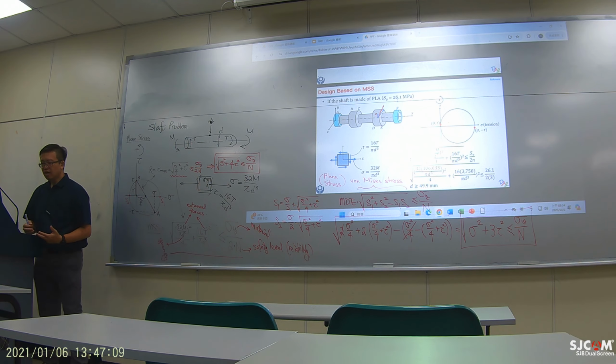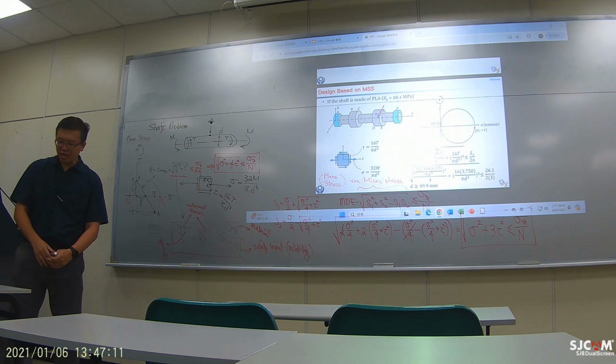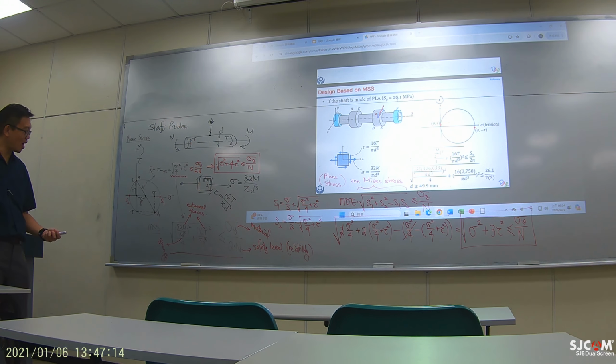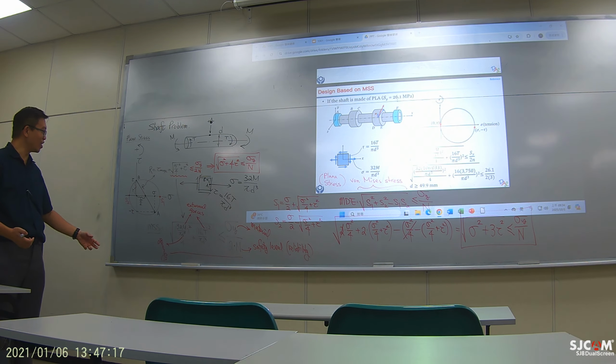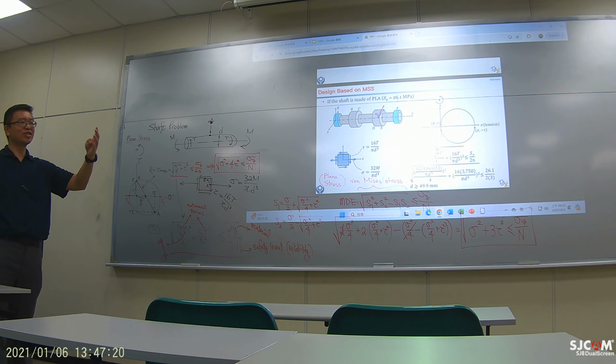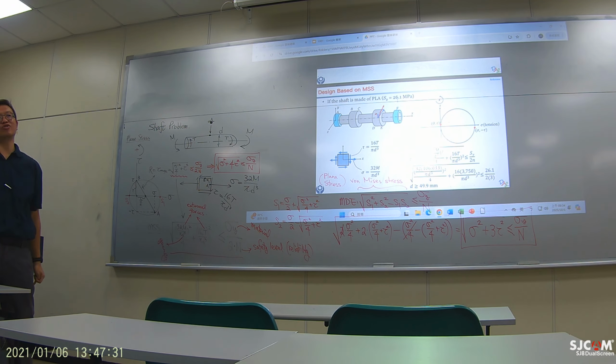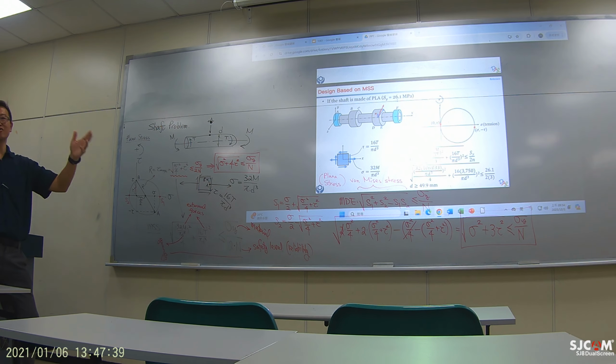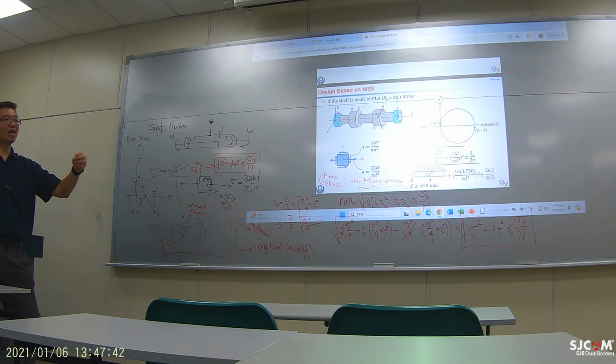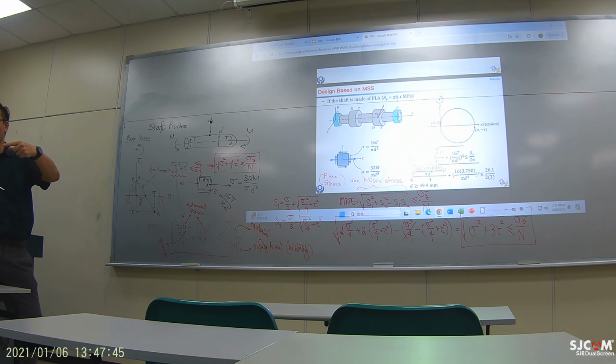So again, another time of reminding you what the design equation is about. It's the relationship between what kind of material you use, what geometry you're designing for your component, and how much loads you're carrying. And with all these combined, how much safety level you can have. And when the safety level is equal to 1, you are designing for yielding. It's about to yield. But if you have a safety level larger than 1, then you have some safety margin. Okay?